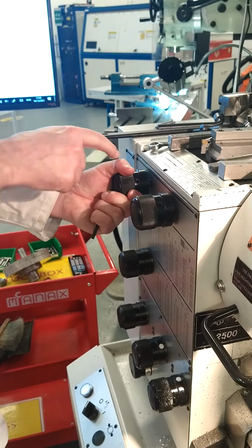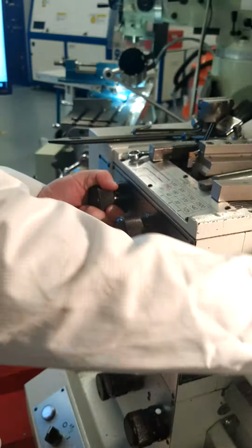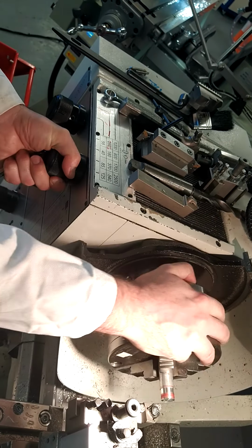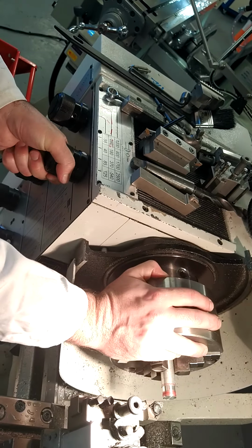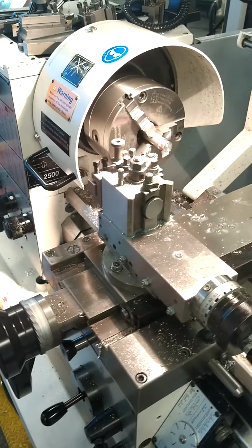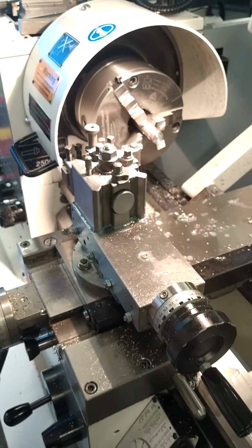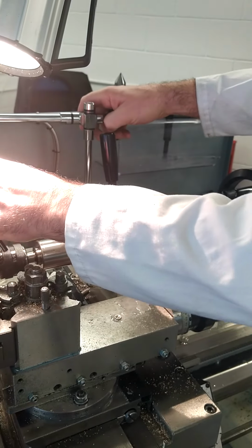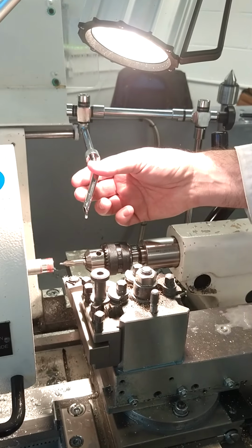To do that, again, I need to twist the lever over and then move this selector along this column to highlight the 800 box. So I'm rotating the chuck and twisting the lever at the same time to get into the gear of 800. I'm in position. I'm going to move the turning tool out of the way. I want to center drill a small hole here for a pilot hole. So I push forward the chuck, and now we're looking at the coolant for the very first time. The coolant gets applied onto the tool and not onto the work.